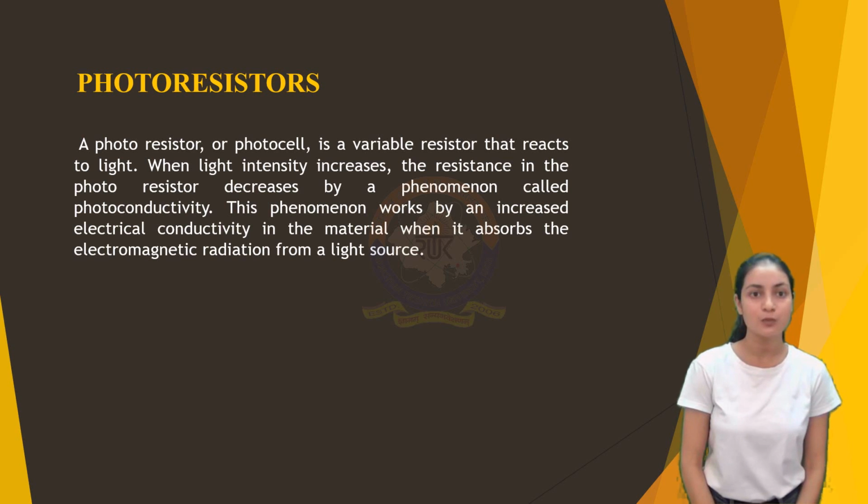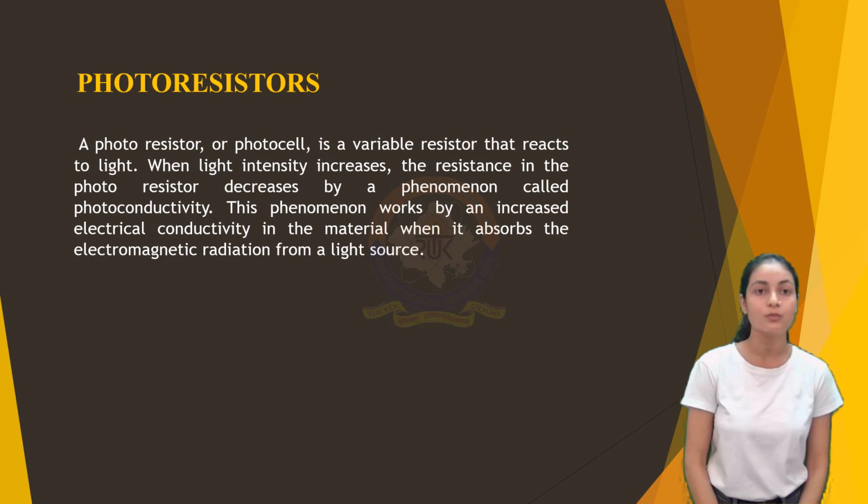Since the first positioning mode is solely relying on the photoresistors, it is important to achieve a reading that is as accurate as possible. Therefore, it is of great importance to place these photoresistors at an optimum position. The self-aligning solar panel uses 4 units of photoresistors, one on each side of the solar panel, to determine the repositioning. This way it is possible to secure the correct direction.